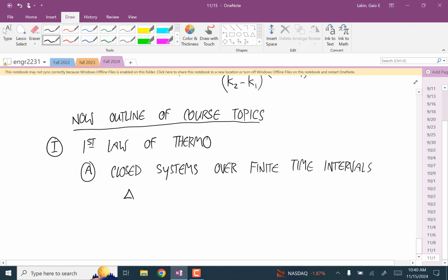So this said the change in energy is equal to Q minus W. And it's often the case, you know, look for reasons to believe in a given problem that this change in energy is just a change in internal energy. But remember, that's not a specific internal energy. So if you're doing everything in terms of specific internal energy, which we almost always are, you have to multiply by mass for that.